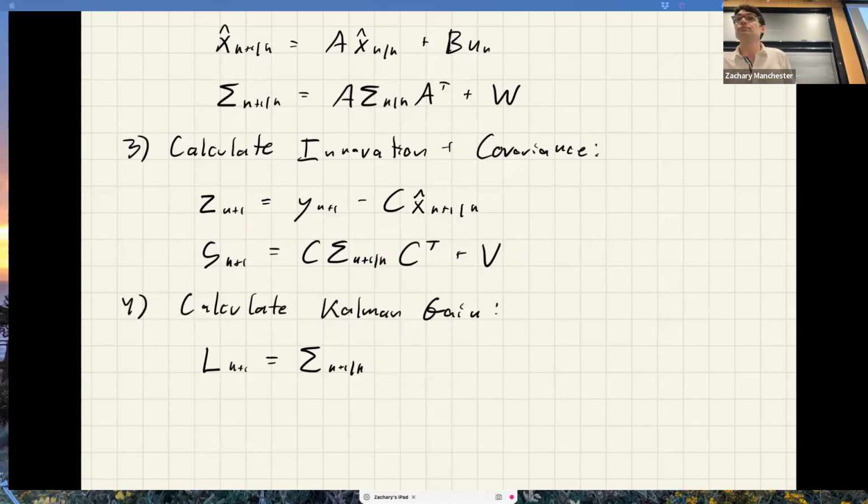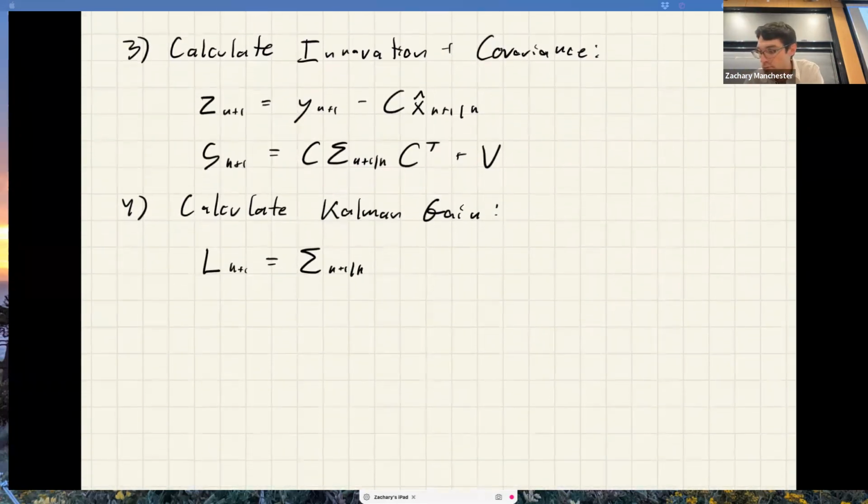Are the two sensors updating the same state estimate, or holding independent state estimates? The same state estimate. You just have to make sure the times line up. If you're going to do a measurement update, you have to use the correct X hat of T. So maybe it's more helpful to think about that part in continuous time. You have a continuous time ODE for the prediction, and you run that to whatever T corresponds to when a given measurement was made, to do a measurement update.